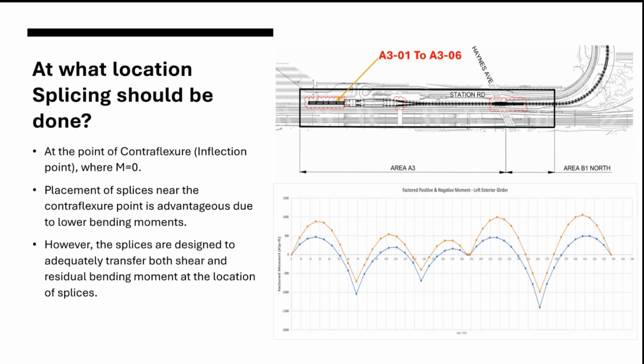And the actual length of the member is decided by the practical limits of trucking and transportation. You can go up to like 140 feet if it's a plate girder, a built-up section, meaning they can build a 140-foot length of an entire girder segment as a single piece, load it up onto a truck and deliver it to the site.